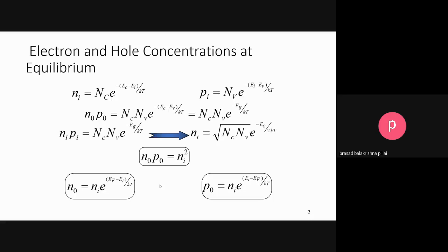Those cases we will discuss very often with a quasi-Fermi state, meaning it is not in an equilibrium state. So very often we discuss a Fermi energy or Fermi function for the non-equilibrium condition also. But the Fermi function, as we understand, is discussed mainly for the thermal equilibrium condition.